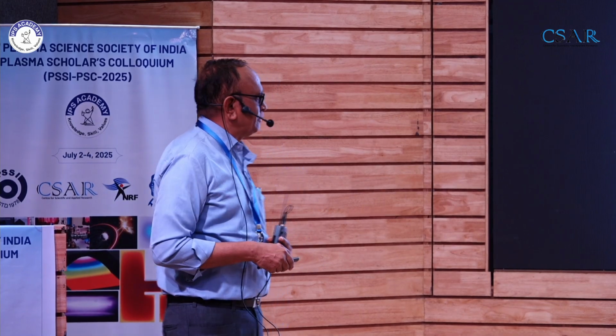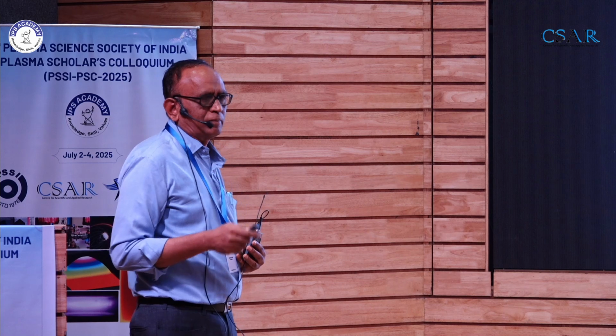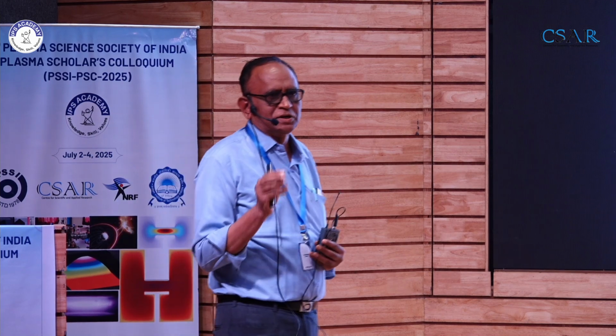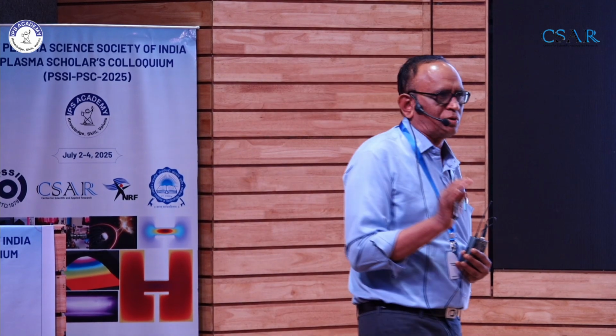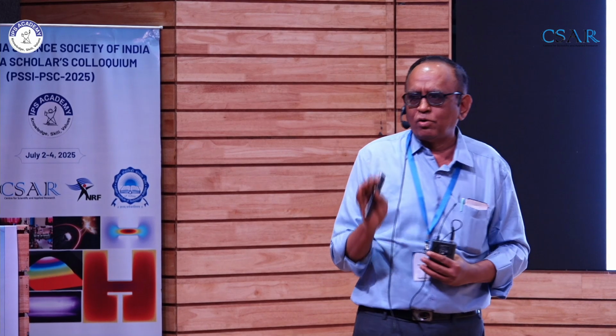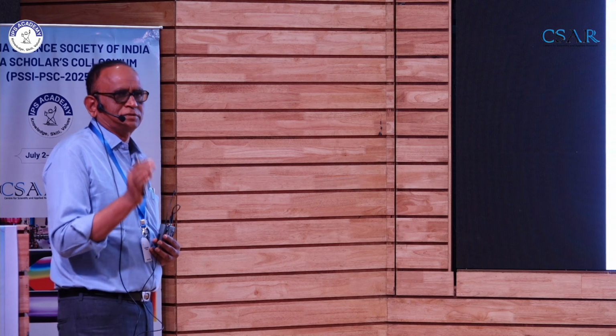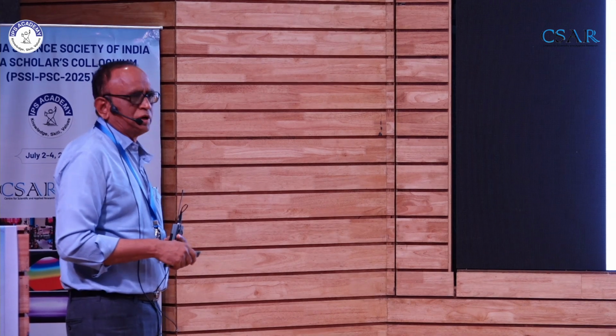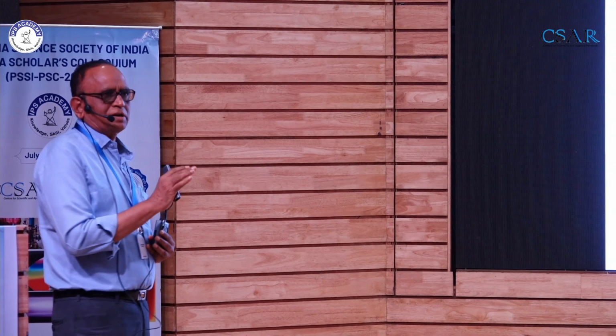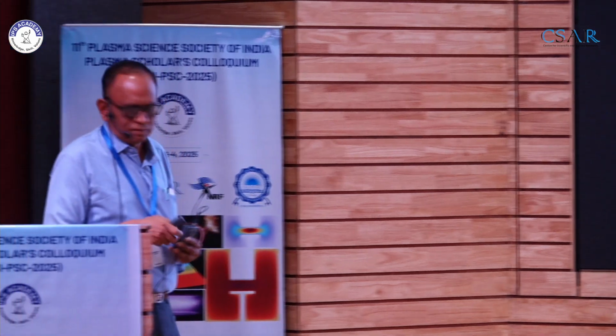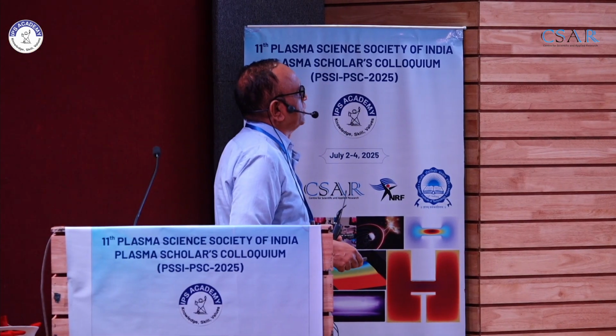But if you use plasma as a medium, particularly low pressure plasmas, then at 550 degrees centigrade, you can deposit excellent quality titanium nitride coatings. And nowadays, all these titanium nitride coatings, titanium aluminum nitride coatings, etc., are basically deposited by plasma assisted CVD and PVD processes. And this is a classic example of how the low pressure plasma medium plays a role in processing